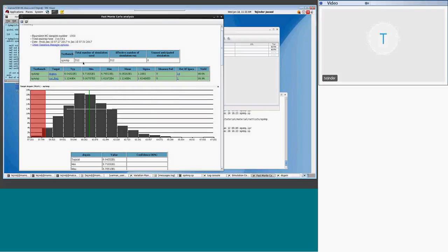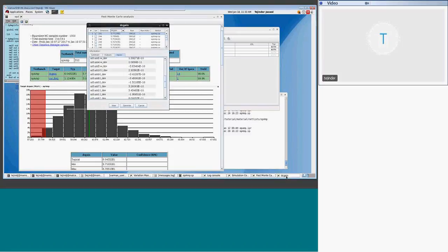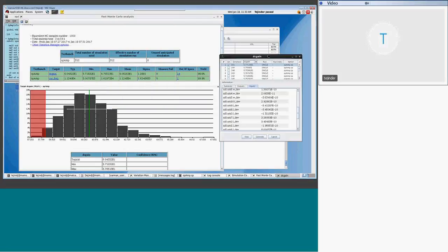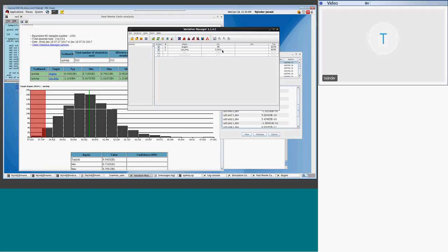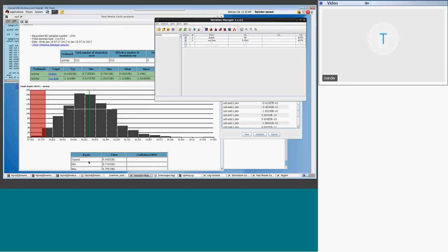Yeah, 312. Okay. My question is, you see that the DC gain has 14 out of spec, so you're trying to tweak it. The out of spec is only on the gain, indicated by the LSL. You can see here the red part indicates that we have simulations outside your specifications. If you remove this LSL, you'll not get any out of spec.